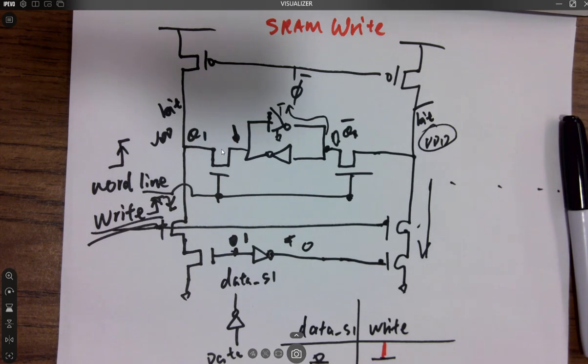You compile it, and it will generate a netlist or digital circuit using these SRAM cells, which were optimized by the foundry, like TSMC or other places. They already designed the schematics and layouts for you, which are optimized because these are repetitive structures, and they know it works. It's giving you great yield, right? So you have to use a memory compiler to design that, and then place it in your design as your RAMs.